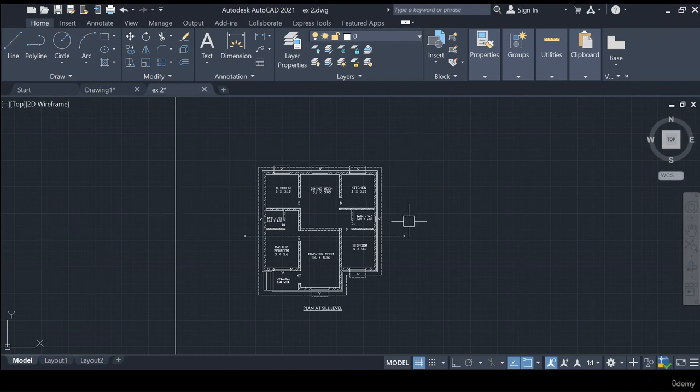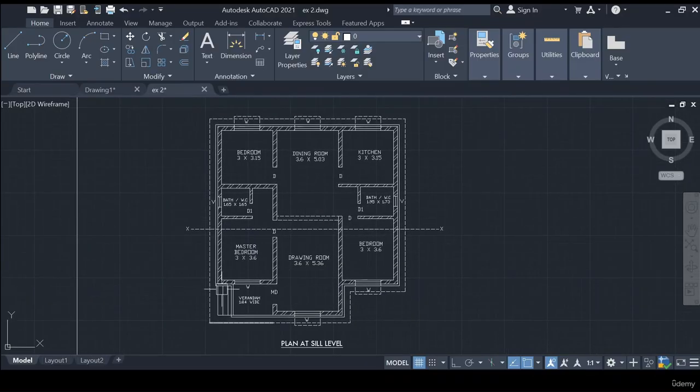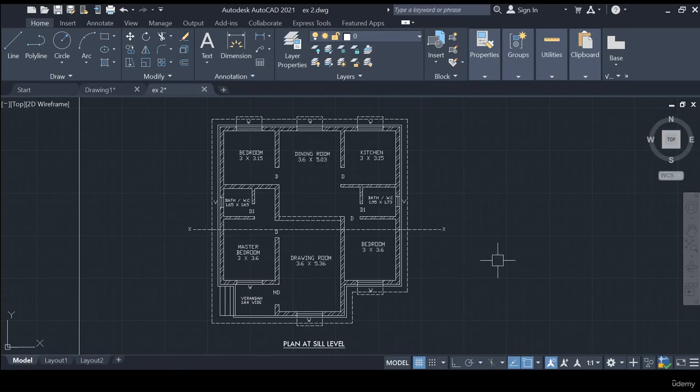One more exercise we started has a building plan, elevation and section that we need to draw. In the last video we completed the building plan, using the line command, the offset command, the edit commands and tool commands. This is our basic presentation drawing, which we need to minimally give to the site.